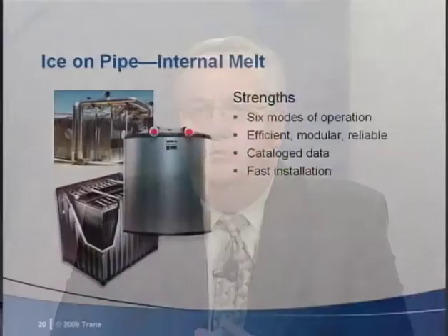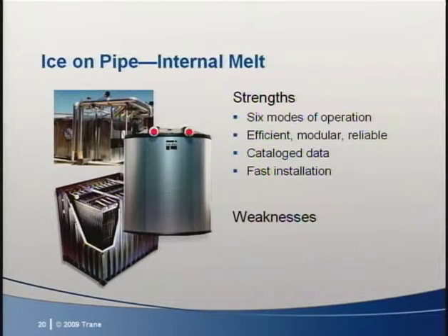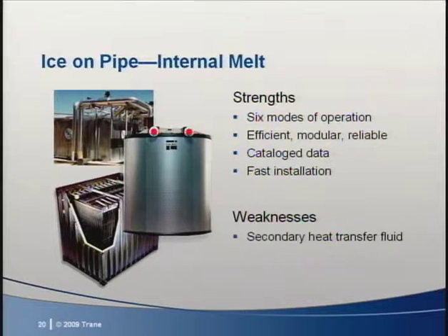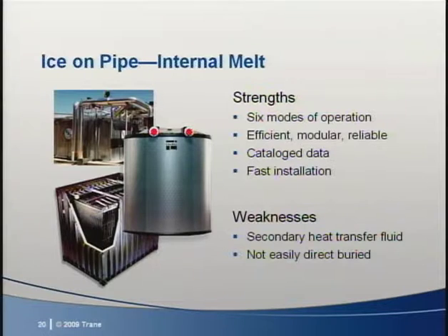The other ice storage technologies that I mentioned are not easily configured to provide the most viable design strategy, partial storage, and they tend to be custom designs which add design and installation complexity, increasing first costs. No systems are perfect, and internal melt systems are no different. Secondary heat transfer fluids are necessary, and because of the modular concept, direct burial is not as simple as digging a hole. Let's take a closer look to get a better understanding of internal melt systems.